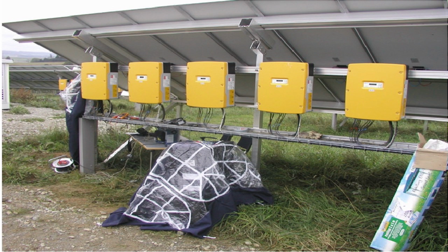Advantages. Poor performing panels don't bring down the production capabilities of the whole PV system. Easy to identify when an individual panel is flawed and in need of maintenance or replacement. Disadvantages. A costlier option than string inverters. Maintenance of microinverters is complicated by the fact that they are located on the roof.